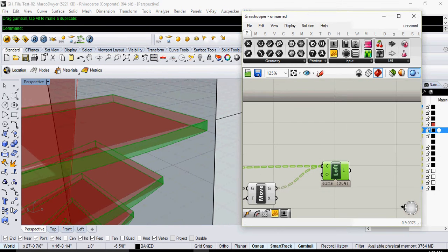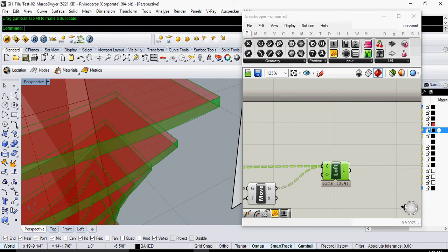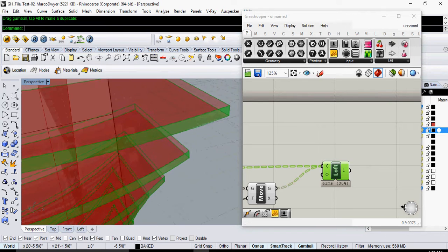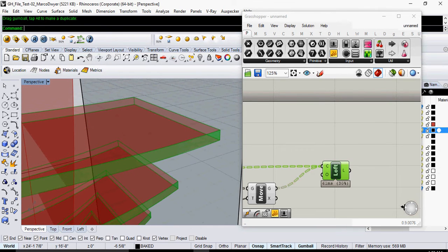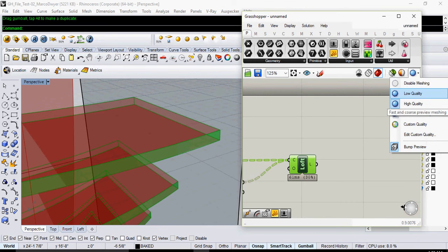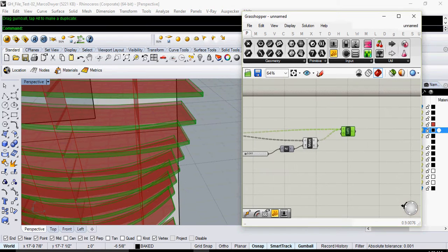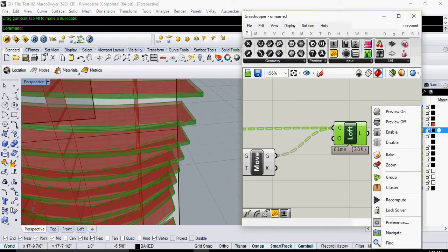It's important to loft it in this case and not extrude it. Change the quality really quick. So it's important to loft it and not extrude it because it will make this exact curvature loft to that one. If you extrude it, it might be off, but theoretically it shouldn't be off. But just in general, lofting is a lot better. So now we have this loft, I'm going to just group it.